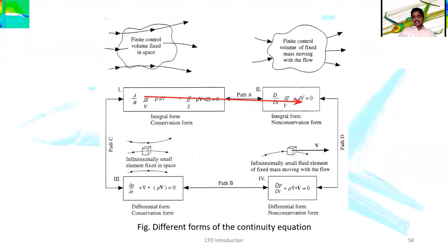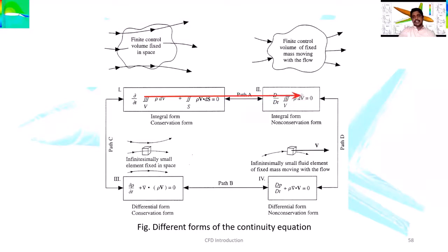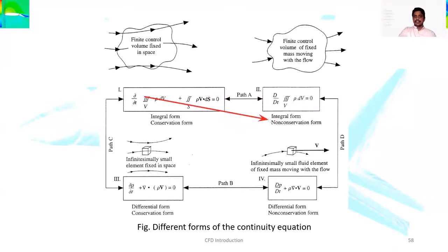How it is being addressed in that equation is, here the volume, so that is the change in the volume, which is addressed in this equation, that it is varying with respect to time. The change in the volume is happening in all directions, that is Vx, Vy and Vz, the xyz direction, the volumetric change. But here we are addressing it with respect to the variable of the volume, which made it a non-conservative form of equation.